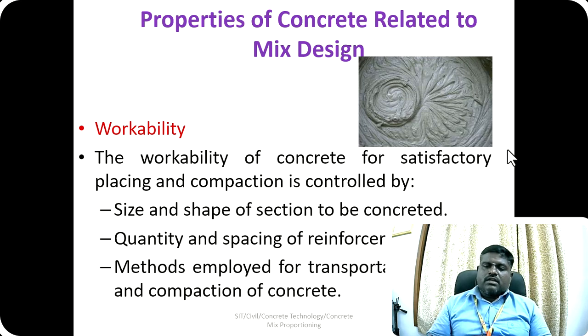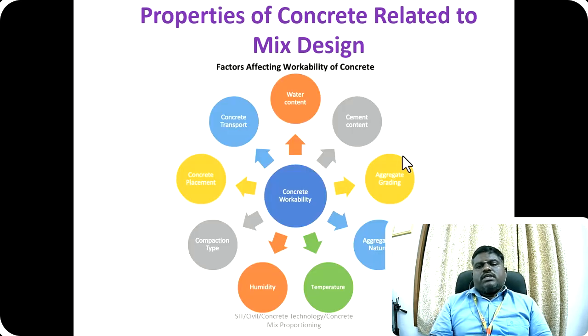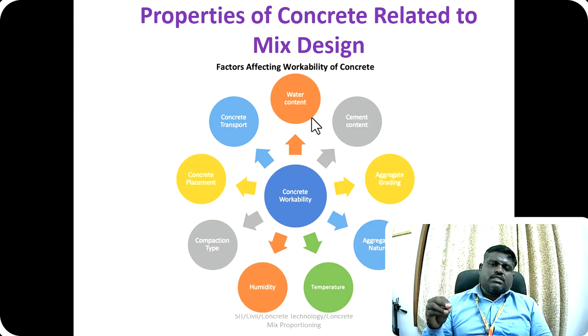So based on the method of transportation, based on the spacing of reinforcement, and based on the section, the workability of the concrete is affected. Okay. So these are the factors which affect the workability of concrete. So generally the concrete mix proportion is mainly influenced by workability. So based on the required workability, we will design the mix.